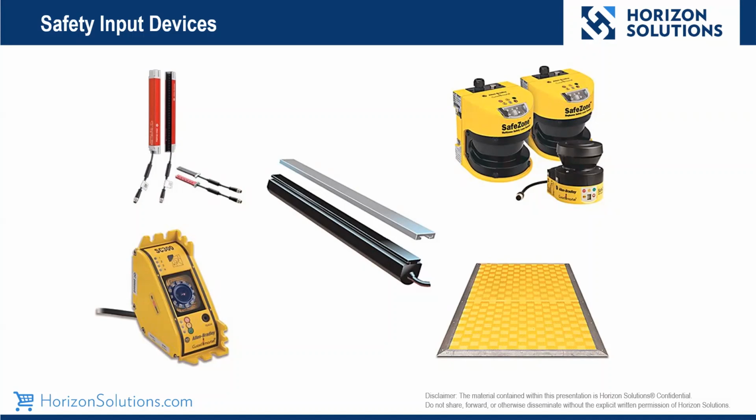One thing to note here is that the smaller your object resolution, the lower what's called your depth of penetration factor is going to be. The depth of penetration factor is how far through a present safety sensing object you can move before the output is tripped.